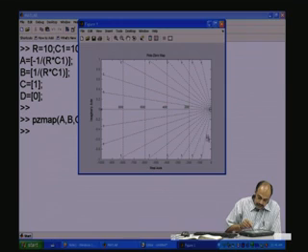Now, this contains a lot of vertical and horizontal lines, and also radial lines. What it basically means is that if there are complex poles, these radial lines indicate the damping. If it is on the real axis, it is well damped, over damped in fact, and if it is on these radial lines, there will be some oscillation before it gets damped.